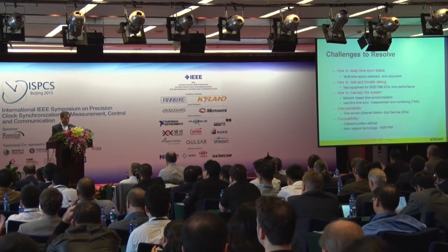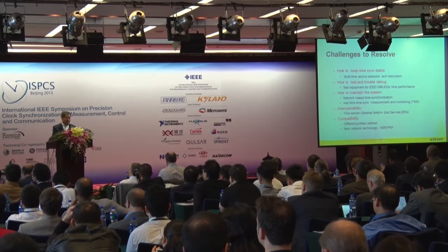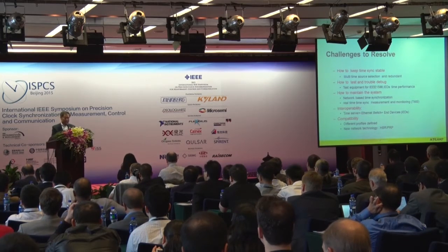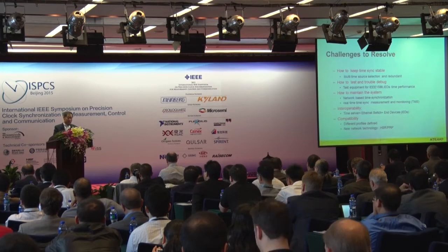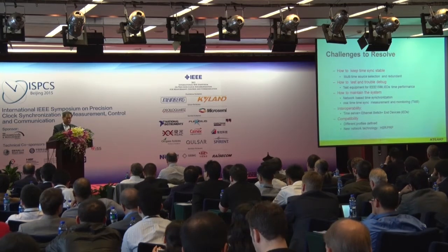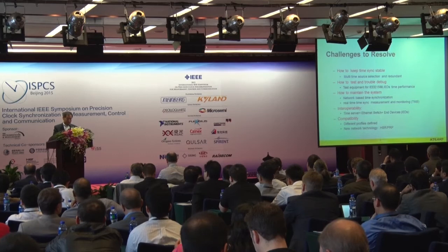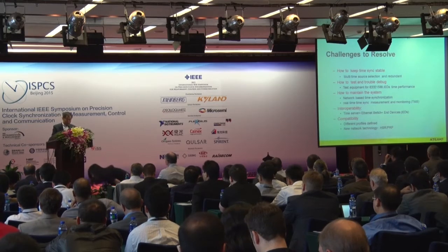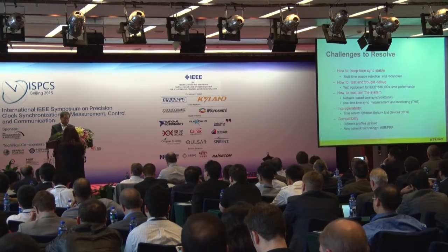Also in the substation, we must have interoperability, such as between the time server, Ethernet switch, and some IEDs. We must keep all the IEDs synchronized. Capability differs, so different profiles are defined.